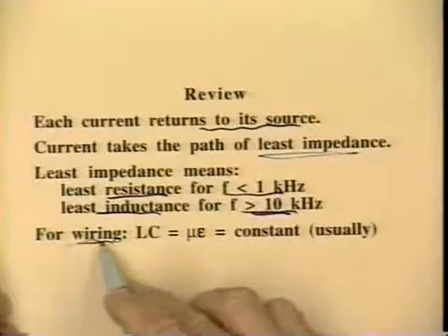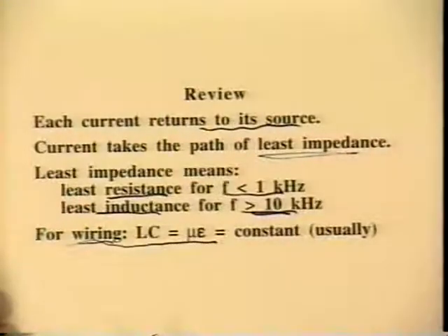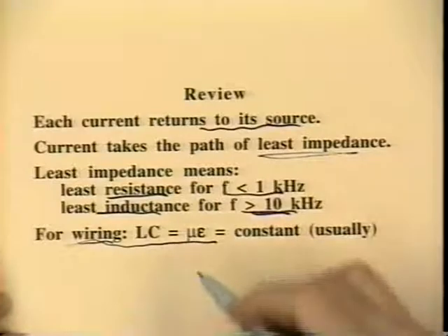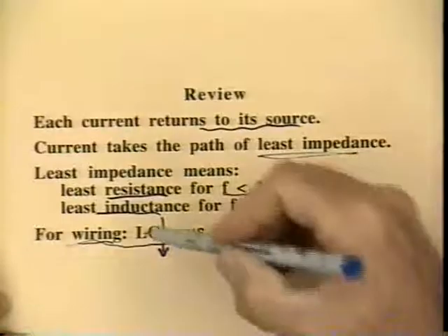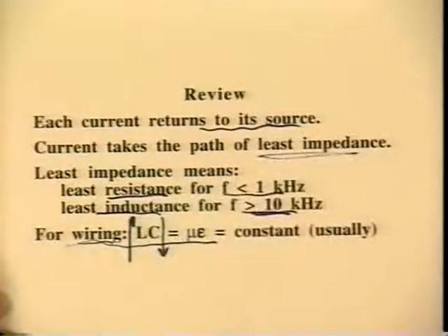So this is a very useful formula to help us keep track of when we're going to have trouble with inductance. If we're doing something that we realize reduces capacitance, we've got to keep in mind that that is increasing the wiring inductance, and that could be a serious matter for us. We may not want to do that.